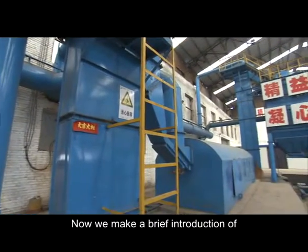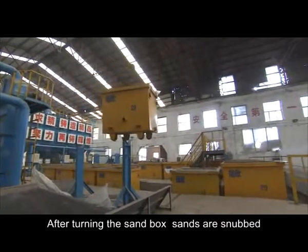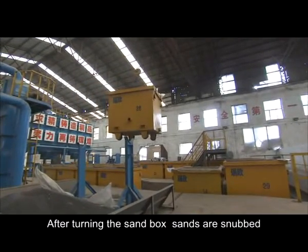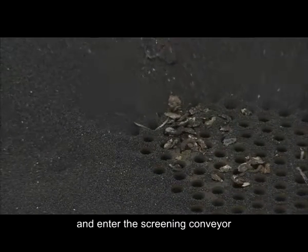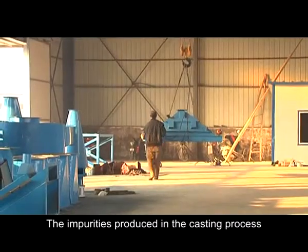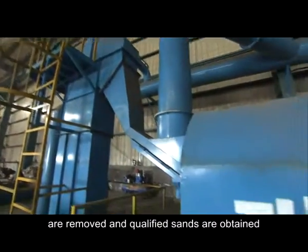Now we make a brief introduction of the sand processing flow. After turning the sandbox, sands are broken up first by the water cooling shakeout machine and enter the screening conveyor. The impurities produced in the casting process are removed and qualified sands are obtained.